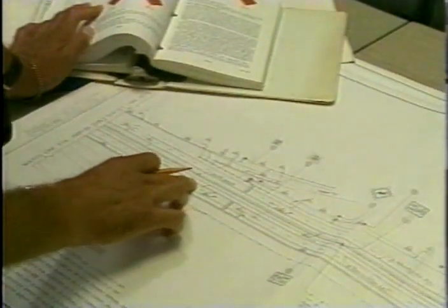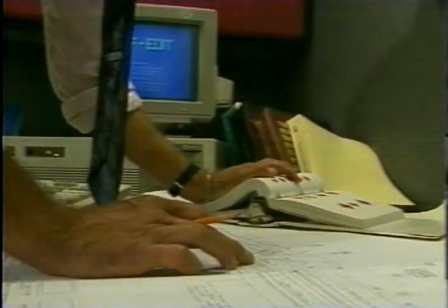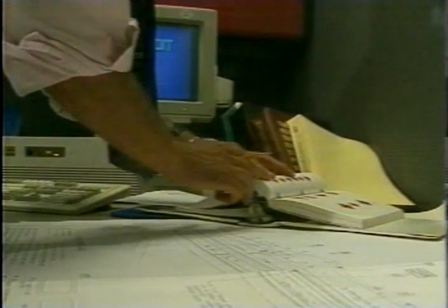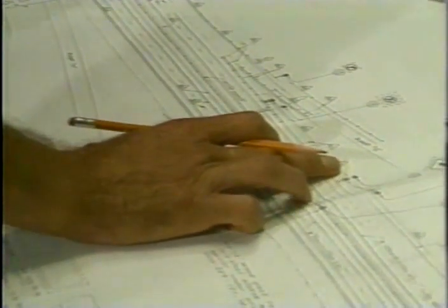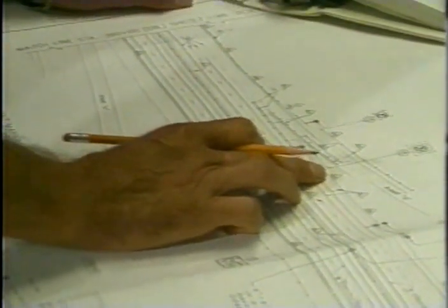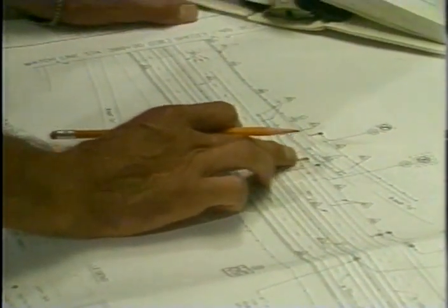Planning for traffic control has one ultimate goal: maximize safety and convenience at a reasonable cost, and consider the hazards and problems involved. This means minimizing accidents while maximizing convenience. A traffic control plan is a blueprint for handling traffic through a work zone. It is often a legal requirement. In fact, it is required for all federal aid projects. It should include traffic control strategies, staffing requirements, use of specific devices, and design of geometric features such as tapers.